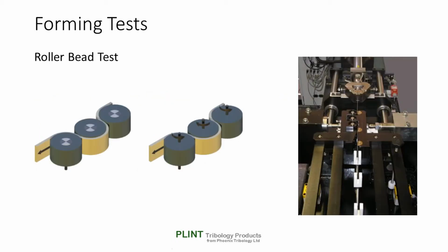Fixed and rolling bead tests are performed with the same tooling and rollers. To convert from fixed roller bead to rolling roller bead, anti-rotation pins on the rollers are removed. A program will start with fixed bead tests with the tooling rollers clamped against rotation.